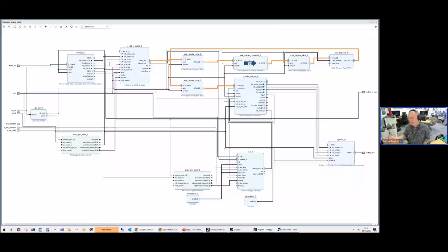And no, you can't. The Vivado IP is specific to AMD FPGAs, obviously, because it uses IP cores and macros and functions that are unique to AMD devices. So, for example, the DSP48 or the block RAMs or such like, it specifically calls up those, which wouldn't have the same features or same availability or same mapping in other devices.